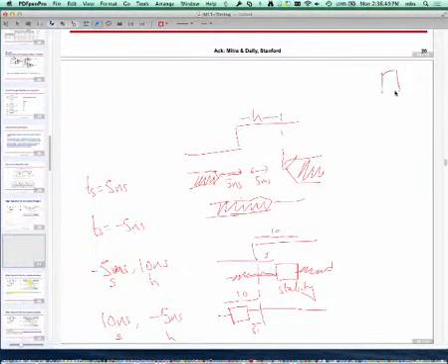Think of it this way. I have my ideal D flip-flop. Let's imagine I put a wire with a 10 nanosecond delay out here. Then it will appear as if the value that this is going to be monitoring is what was there 10 nanoseconds before the clock. Correct? So that's all that is happening here.